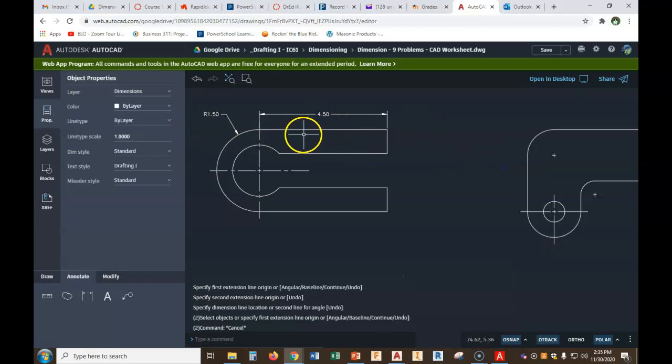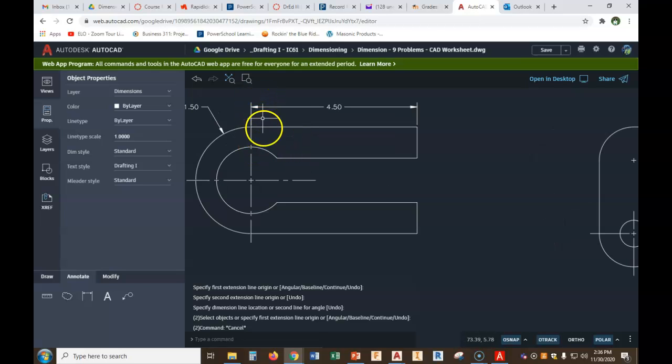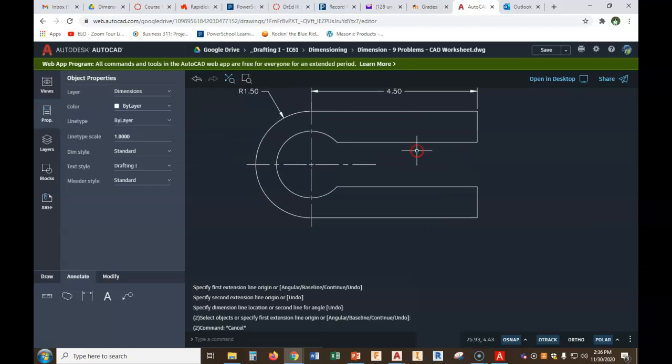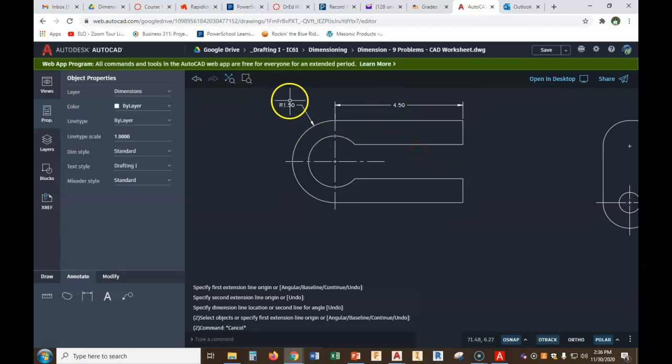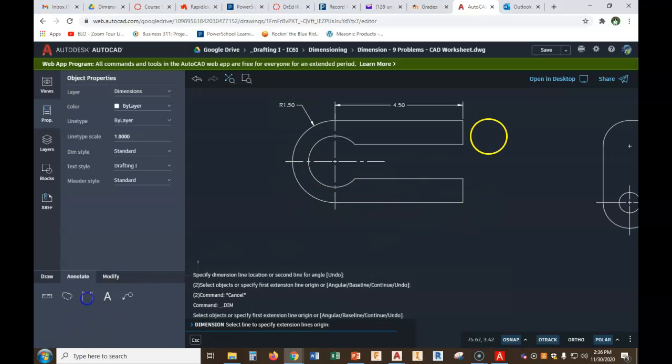These two numbers together give us the overall width. This is one of the few times we're going to make somebody add. Okay? So remember, center line keeps on going, no gap. Here we want the gap. Now, not only is this the overall width, but that radius of 1.5, well, if you take 1.5 to here, 1.5 to here, that's 3 inches wide. We don't give overall height either. Okay? So what else do we need to do?